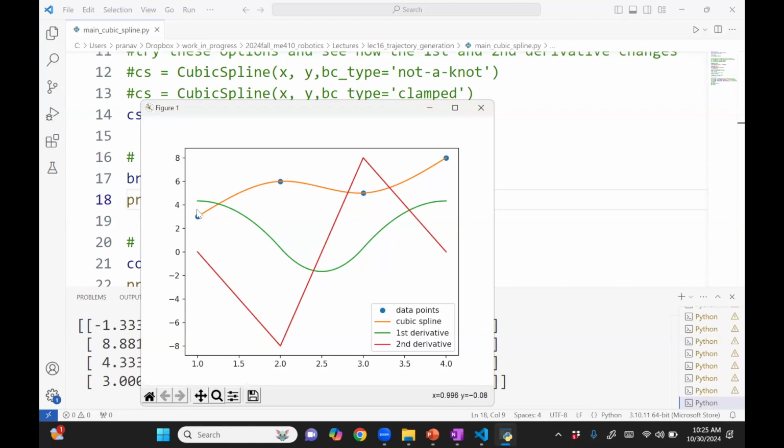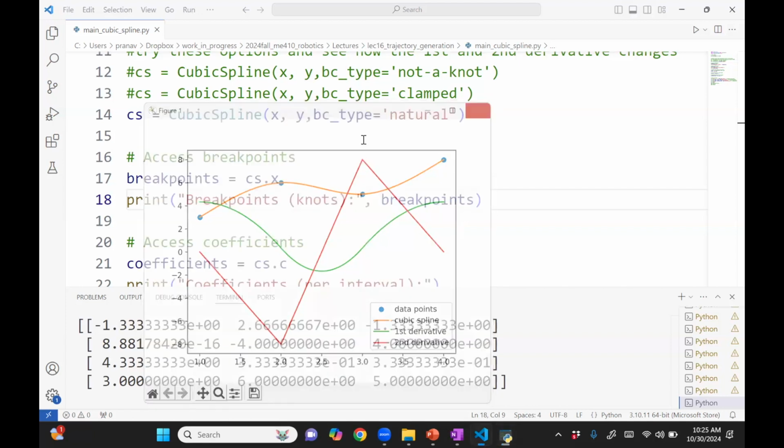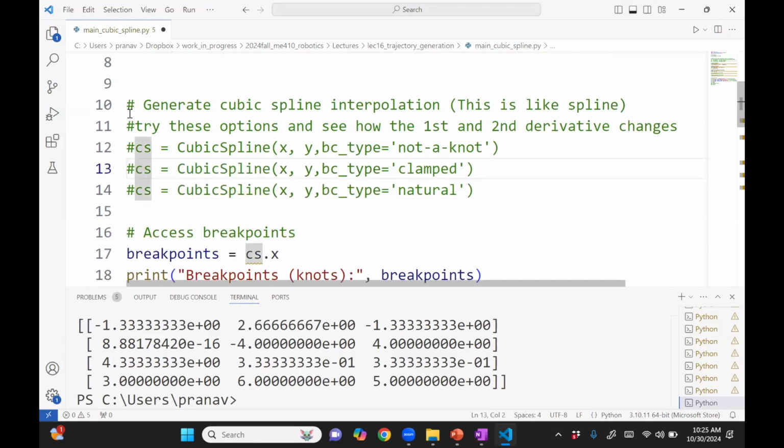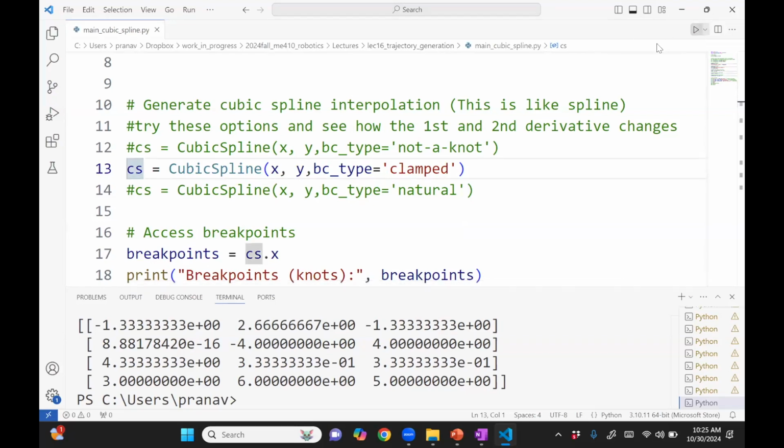Velocity actually jumps from 0 all the way to 4, and then shows this nice smooth curve. But again, when it's here, it jumps from a little above 4 to 0. So it's not good for velocity, but the acceleration is smooth. Okay, there's a kink here, which means that the derivative of acceleration, the jerk, won't be continuous. So that's what you'll get if you use natural spline. Let's change the condition to clamped. Clamped is when the velocity at the endpoints is 0, versus the first one, where the acceleration was 0.